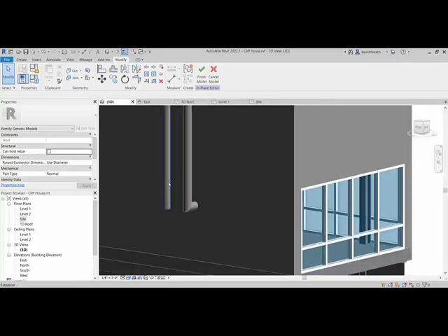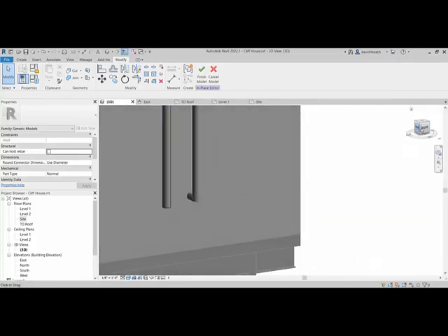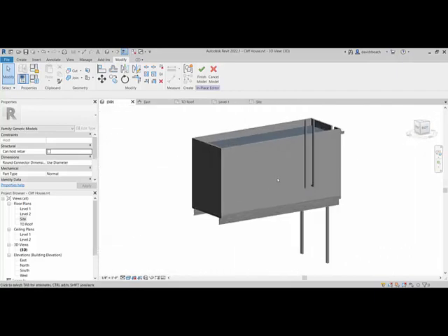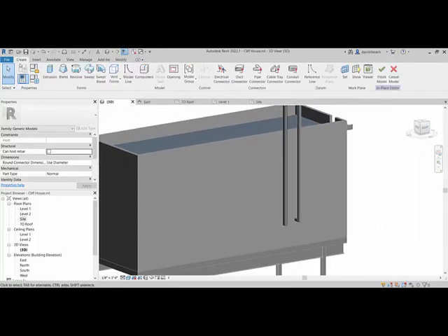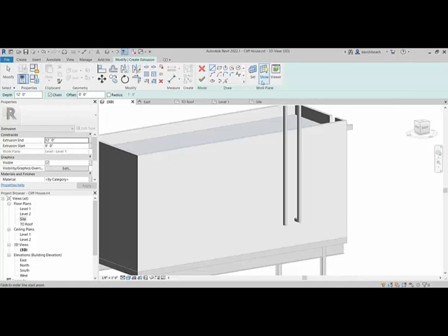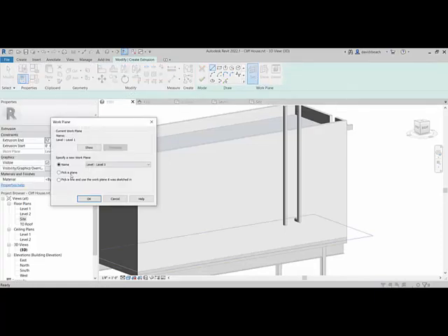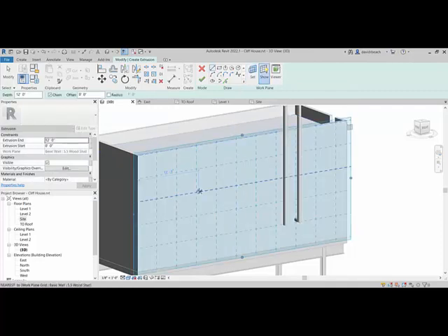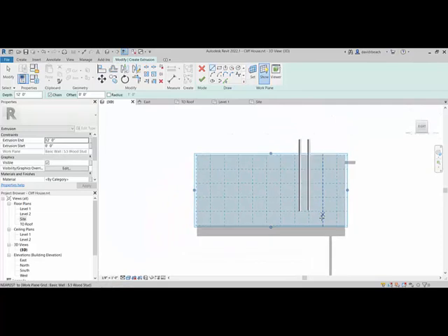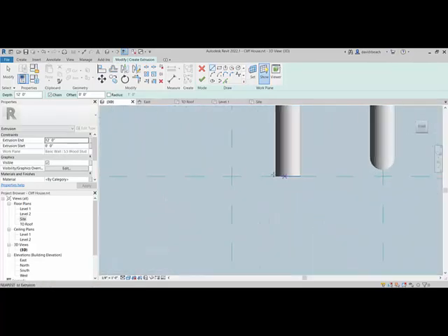So the sloppy way to do something like this would be to say, okay, let's go create extrusion and set a reference plane to that wall, right? And now if I look at that wall, I could come in and do another cylinder just like that, right?